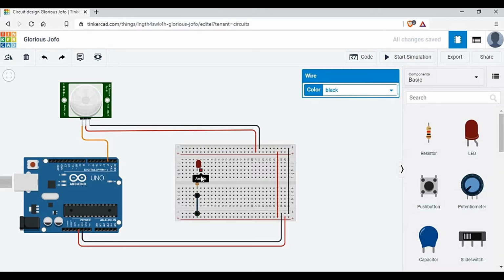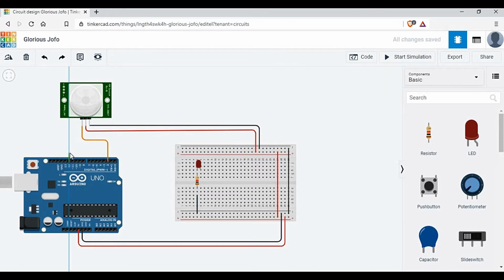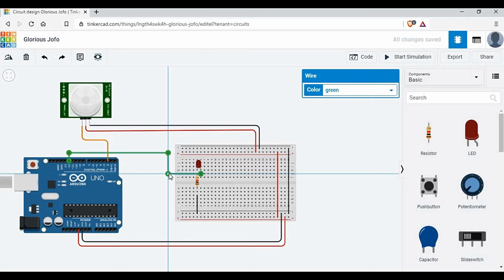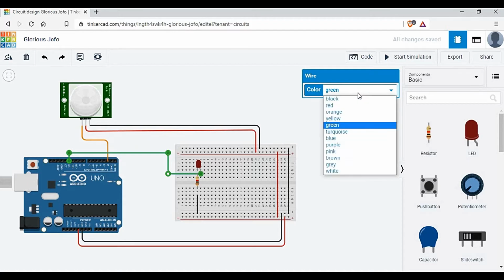Now we have to connect the signal to the LED anode. So I'm going to use the pin 12 here for this. So I'll use this connection like this. So what does this mean? The pin number 12 will decide whether the LED has to be lit or not. So if the pin 12 we can define, you will get the power, the LED will be turned on.